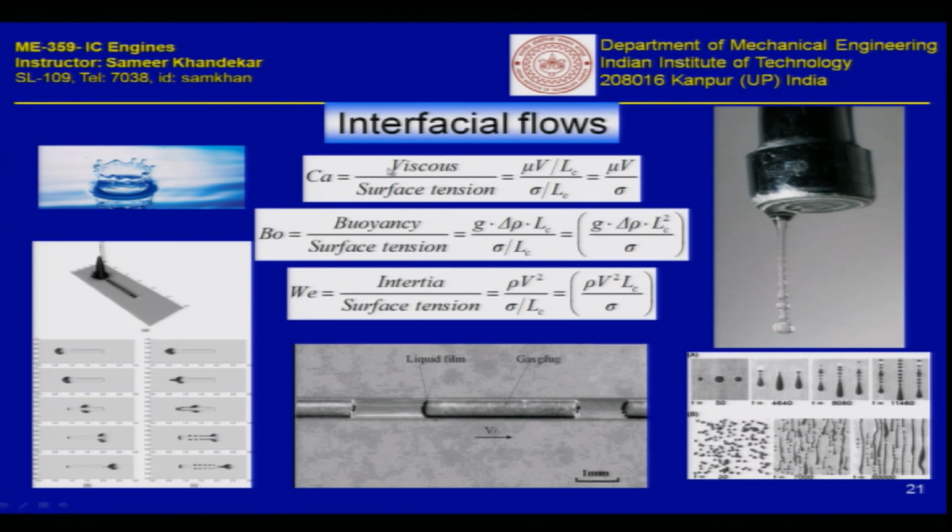One is the viscous force. Now, the viscous force comes because it is a fluid, and as soon as fluid gets in motion, you have gradients of velocities which are created, and these gradients of velocities, as you all know, will lead to shear stress. So, there are viscous stresses. Naturally, the length scales are very small and you will have surface tension. At this particular interface, there will be interfacial excess energy, and this excess energy is manifested as surface tension, which you all know. So, surface tension will also be there.